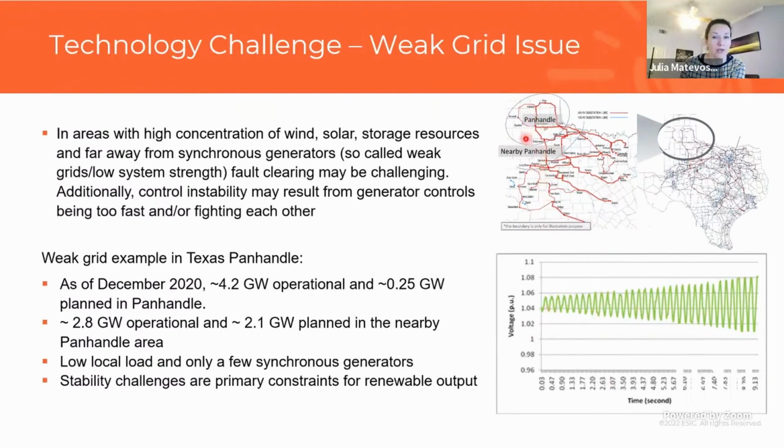And so in real time, they're saying, oh, because of stability considerations, I cannot transfer more than X megawatt from here today. And this is being calculated in the day ahead based on system configuration at the time and based on wind and solar forecast at the time. So they basically look at what production is expected in the area, what is system configuration, what are studies saying can be stably produced in this area. And if the amount that is available is more than what can stably be produced, then all of that generation is curtailed. So that's the most common mitigation today, unfortunately.